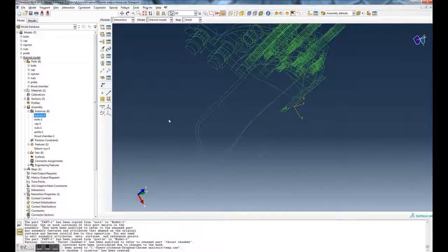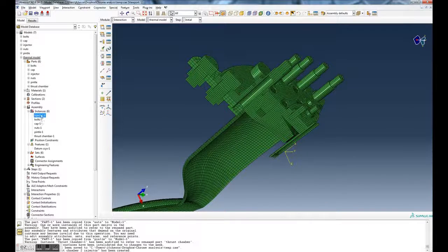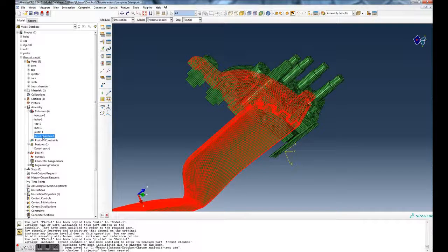Now we need to solve. We're going to solve at the reduced degrees of freedom. So you remember up top here, one of the inputs is for you to supply what degrees of freedom are unconstrained, and there they are, right? So this is going to solve the reduced system. This only works for homogeneous displacement boundary conditions currently, but we can change that.